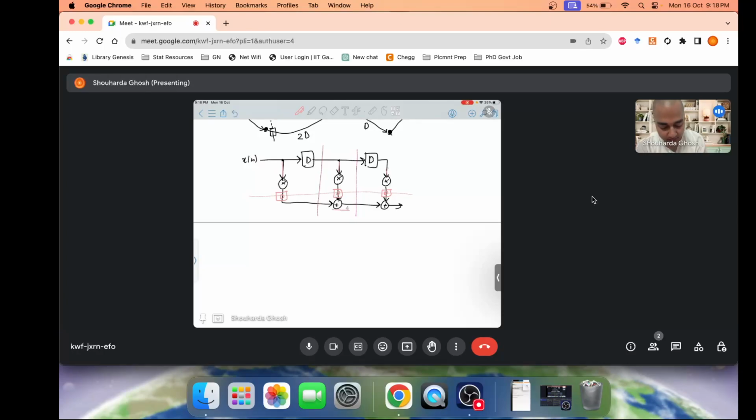So these delays are restricting my path. And then another path I can see over here, one is this, another one is this. So it will be either the multiplier delay or the two adder delay. The first possible delay is the maximum of Tm comma 2Ta, or if we had n of them, the maximum of Tm and (n minus 1) Ta.